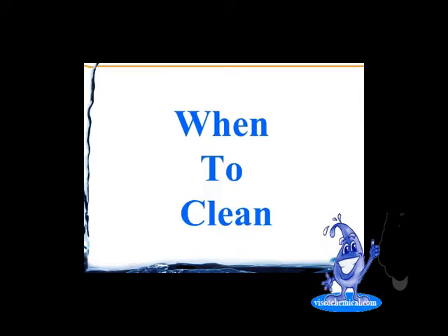So we've talked basically about how we scale and foul. We scale due to concentration, and we inject scale inhibitors to keep us from scaling, or we have water softeners up front.